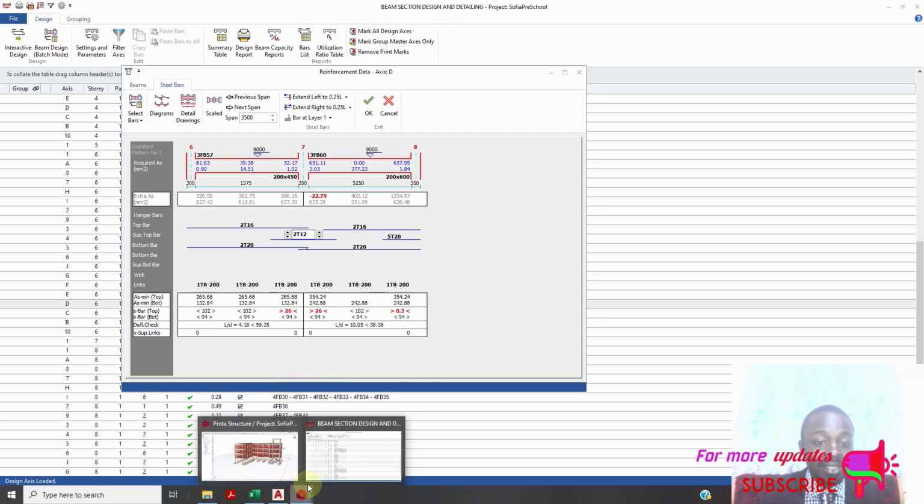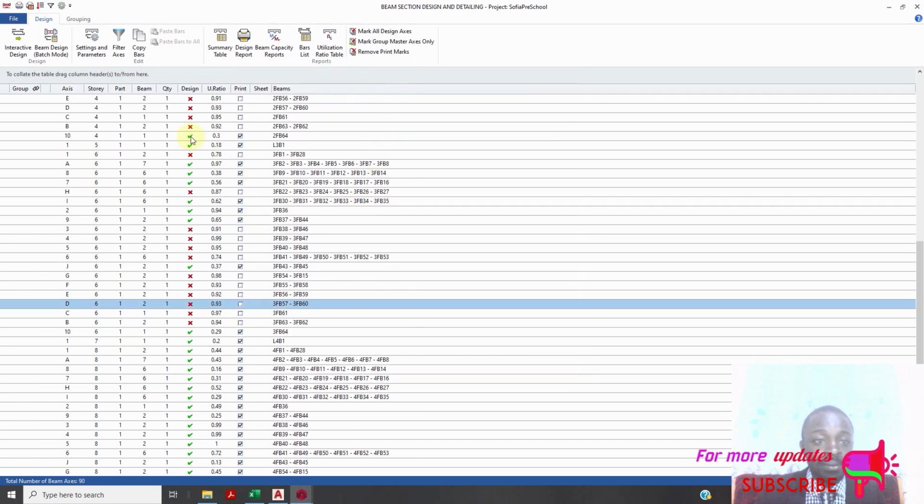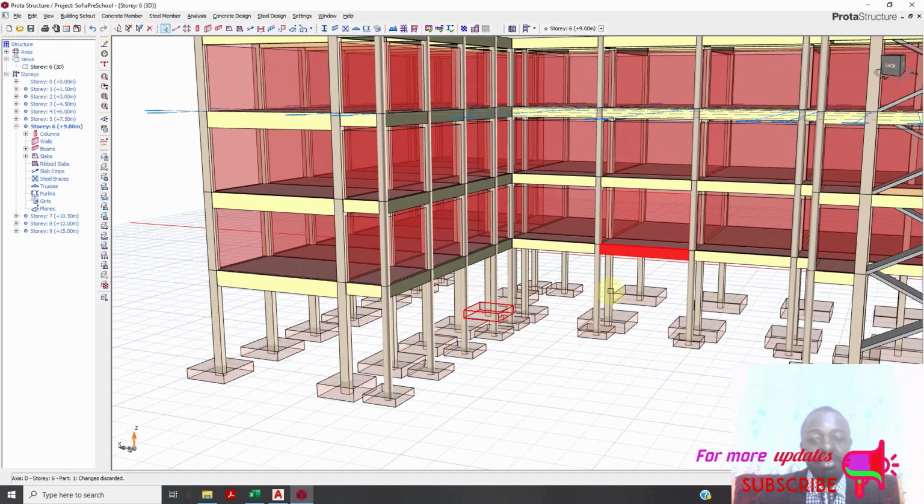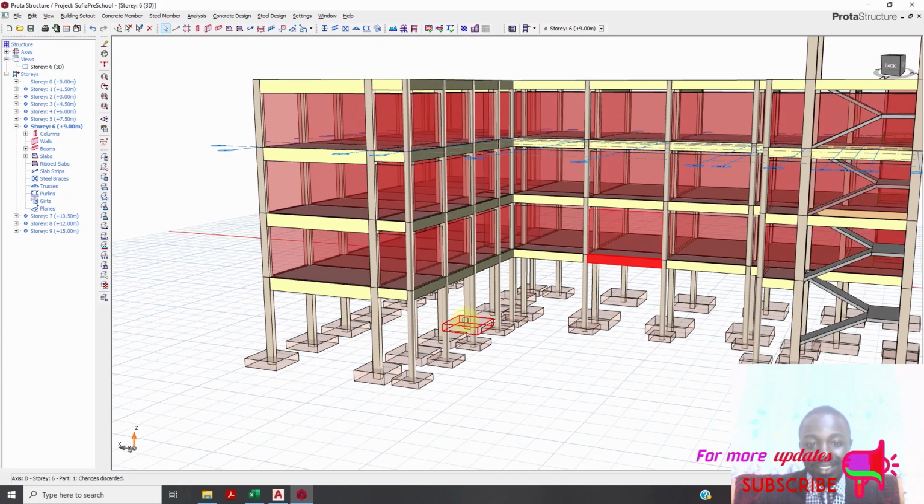It's like it is being supported by those beams, and it's like we're having maybe a parking down here, which is not correct. So this wall is going straight to the ground, and that's why we are having masons and their tools, including the plumb board, to make sure that that wall is not tilted even a bit. That wall is at 90 degrees. It is transferring its load directly through gravity straight to the strip foundation. So that is a very common mistake that engineers make.